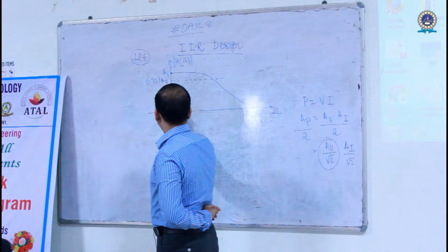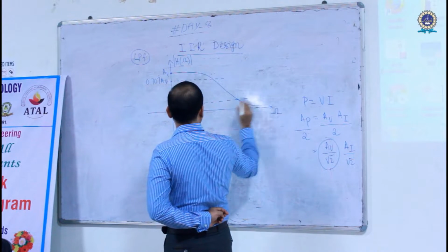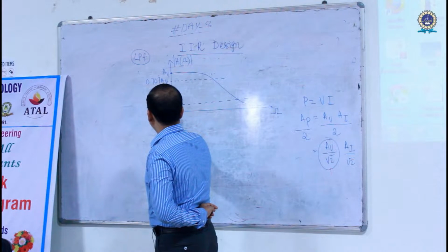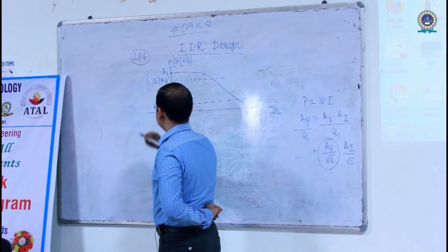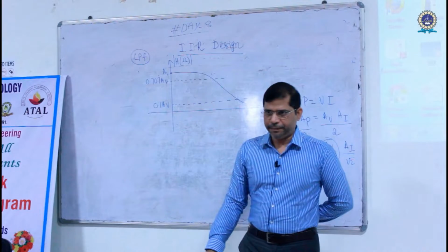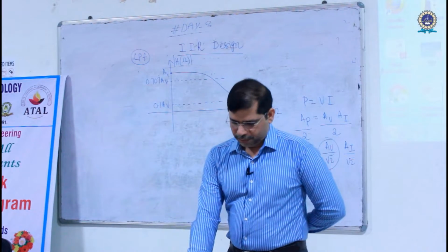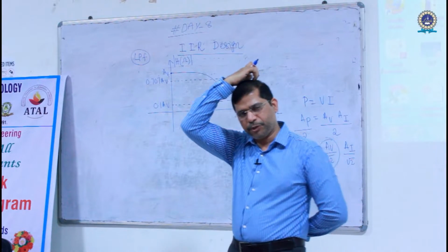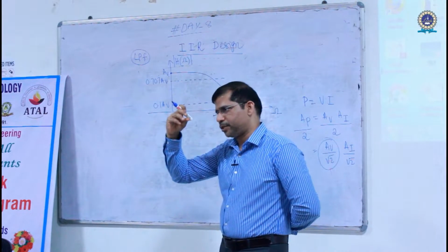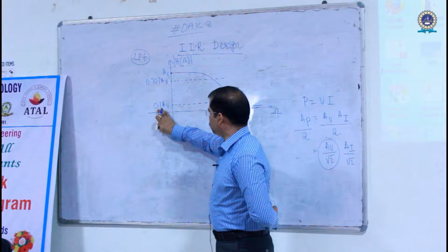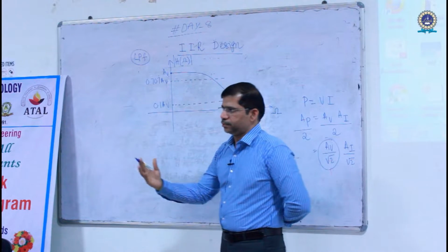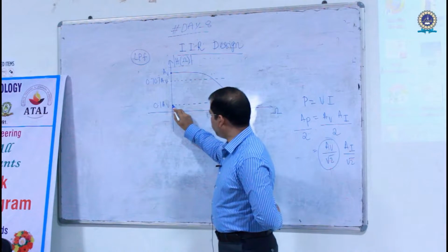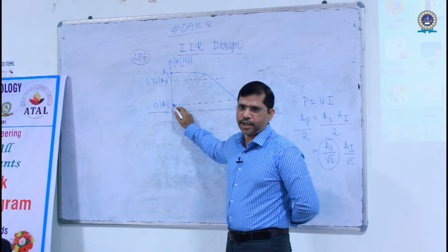And I am going to draw one more line here. So this is 0.1 AV. Why again 0.1 AV here? Rise time versus fall time, because you have to allow a minimum of 10% of the time for the system to reach or respond. So above this, the system starts getting a response.